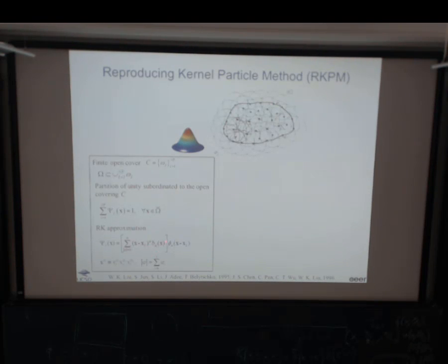Okay, so now, of course, how do I obtain the coefficients here? Now, one thing which I also feel is very unique in this original idea is that you can have this kernel function take different forms of smoothness depending on the physics that you're dealing with. Okay, so for example, if you are dealing with a crack like I'm doing right now, then I'll use something like a step function, something that introduces discontinuities, right? So that you get the right regularity in the approximation. You can do something like a C0 function, like C0 finite elements, right? A hat function will give you C0 continuity. You can go to C1, go to C2, you can go to Cn.